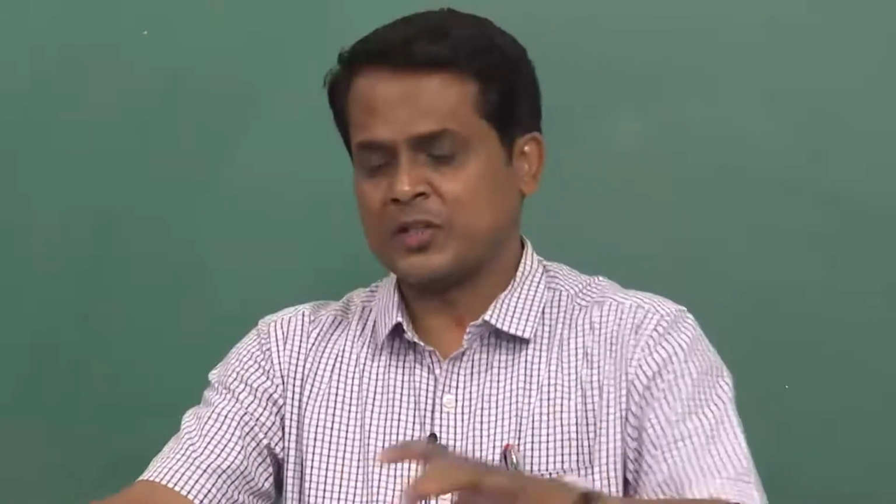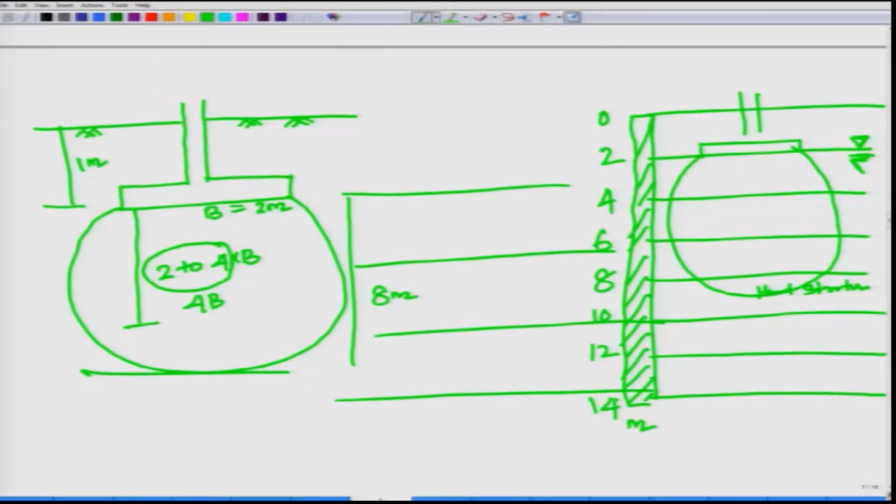So, you go for a soil investigation with tentative dimensions and take a call on how many boreholes and what depth you are supposed to do. Once the borehole has been made, you cross check whatever column load is coming, and at what depth you are going to place your footing below the column. Then the pressure bulb below should be within your safer zone or maybe slightly harder stratum. There are many things I'll discuss as we progress.